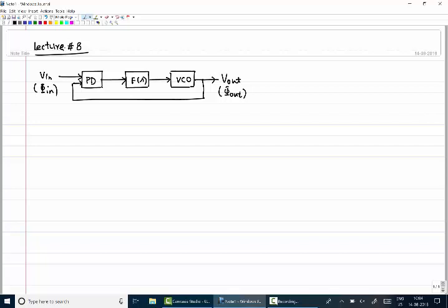Now the phase detector which we have used so far is a sinusoidal mixer based phase error detector, and it's not that this is the only phase detector. There are other phase detectors also. So now we will go into each of these blocks and define some characteristics at the behavioral level. We will look at the circuit level after the behavioral level simulation and the block functioning. So we will start one by one. First one is the phase error detector. We write it as phase detector also.